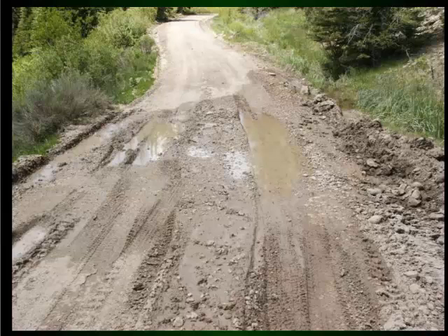This needs to have a catch basin dug out and then a pipe going across the road. This being a low spot, it needs a little bit of fill material over it, a little bit of rock. It'd be a good place for the geotextile. Some people call it filter cloth. Put a short segment so that this mud doesn't pump back up through your rock and contaminate it.